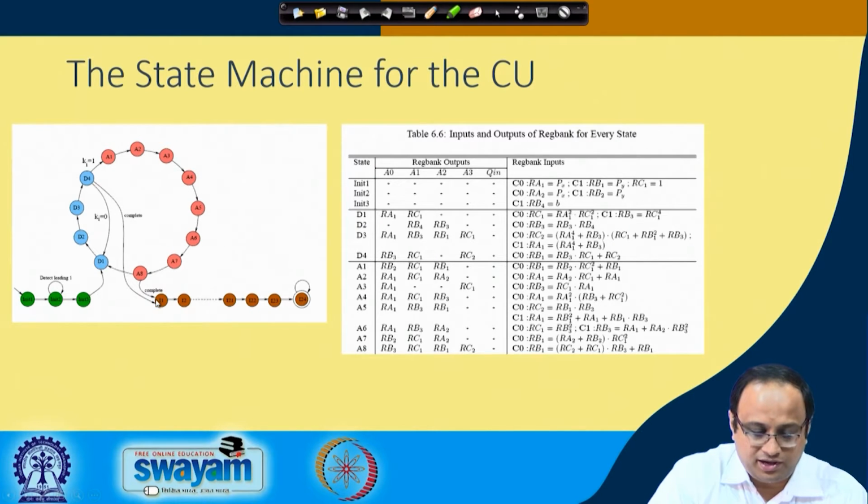And then there is a final step of inversion, where you bring the result back from the projective to the affine coordinates. This is shown here in the brown line, and it turns out to be 24 clock cycles when employing the Ito-Tsujii inversion algorithm, as we have studied previously. So here is a snapshot of the control logic.